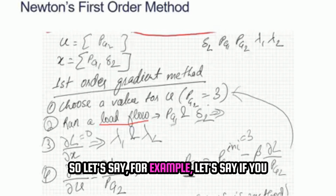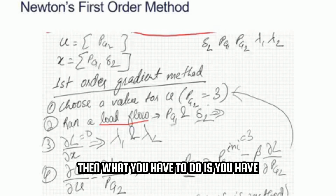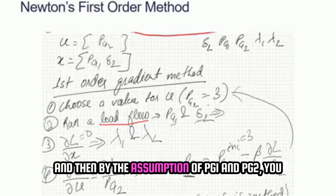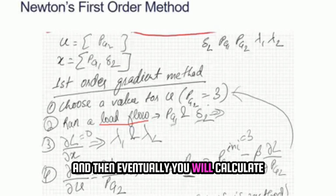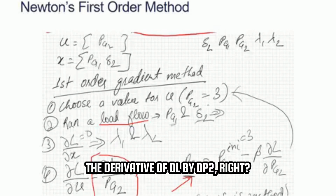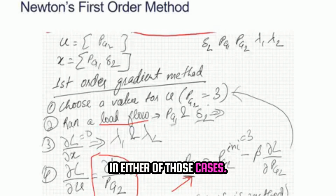So let's say, for example, if you keep PG1 and PG2 both as a control variable, then you have to give initial guesses for both PG1 and PG2, and then by the assumption of PG1 and PG2, you will get the values of delta 2, and then you will calculate the value of lambda 1 and lambda 2, and then eventually you will calculate the mismatch of PG1 and PG2 using the derivative of dL by dP2. Right. So you can make any formulation in either of those cases. So it is up to you how you decide this expression.